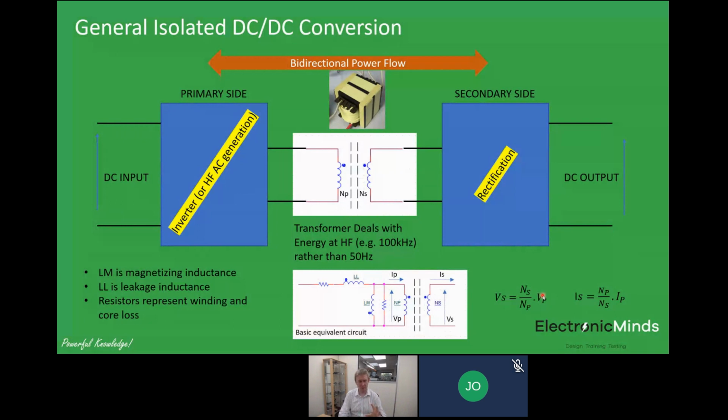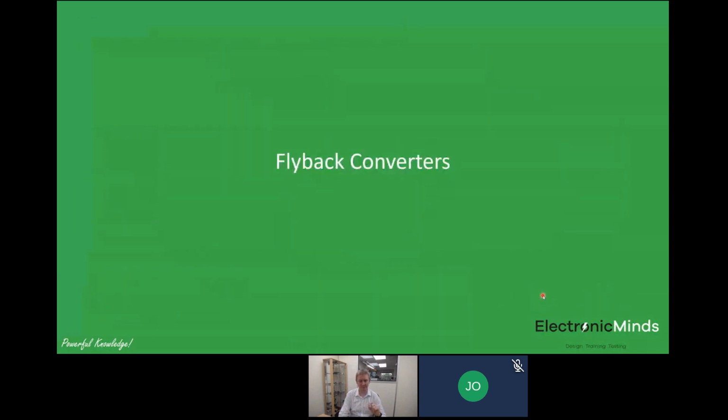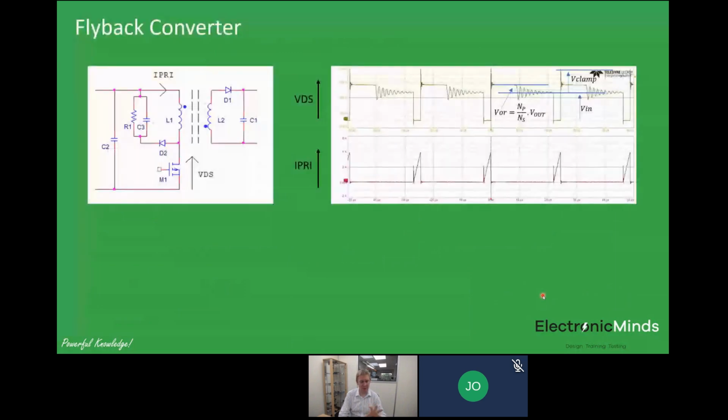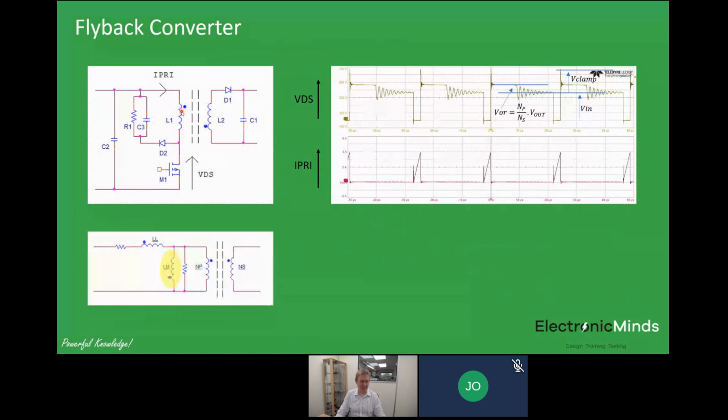Now then, I was going to talk about a flyback converter, and I'm going to show you how we use this particular model to transfer power in a flyback converter. Now, if you've dealt with flyback converters before, this will become quite familiar, but bear with me on this. The way a flyback converter works, this is actually the topology on the top left-hand side of the screen. You can see we've got our transformer element here, which again is our, if you zoom in, is our equivalent circuit. There's a dot polarity, which is to do with the polarity of the winding voltages that we generate here.